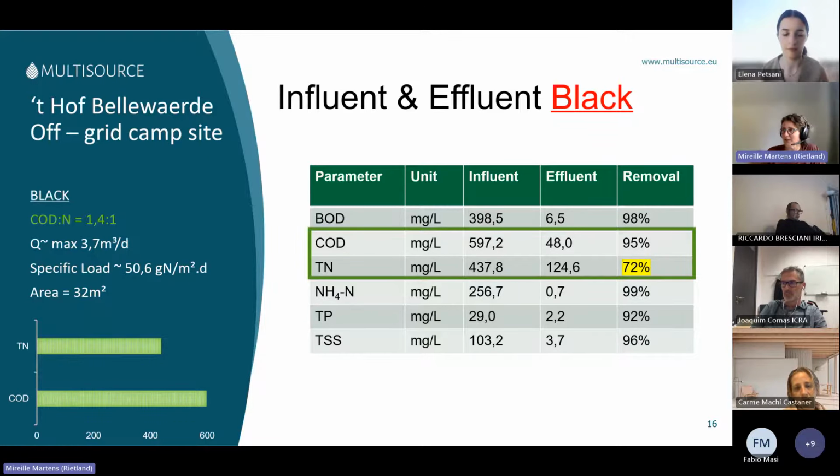And then I have another example, which gives you some insight in extra solutions. So if you want to improve your nitrification, and you cannot do anything with the influent water because there's not sufficient carbon there, there are 3 options you can do. You can add an extra wetland, you can add a carbon solution, or you can recycle your effluent.